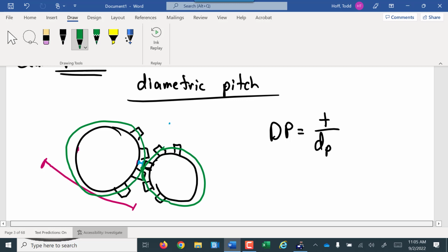Well, you'd have to get into spur gears, and there's a whole ton of formulas for spur gears that you can calculate from the depth of the tooth or the working depth of the tooth, the clearance of the teeth. All of those things can be used to find that pitch diameter. We're not going to get into that here because that would be a 40-minute lecture all on its own. But just know that is the diameter they are talking about, the diameter of the circle of the two circles that touch, part way out of the tooth from the center of the hub.